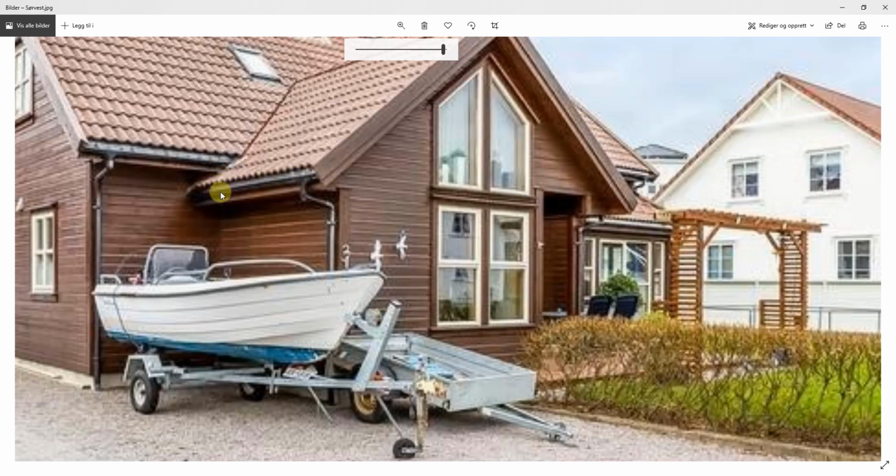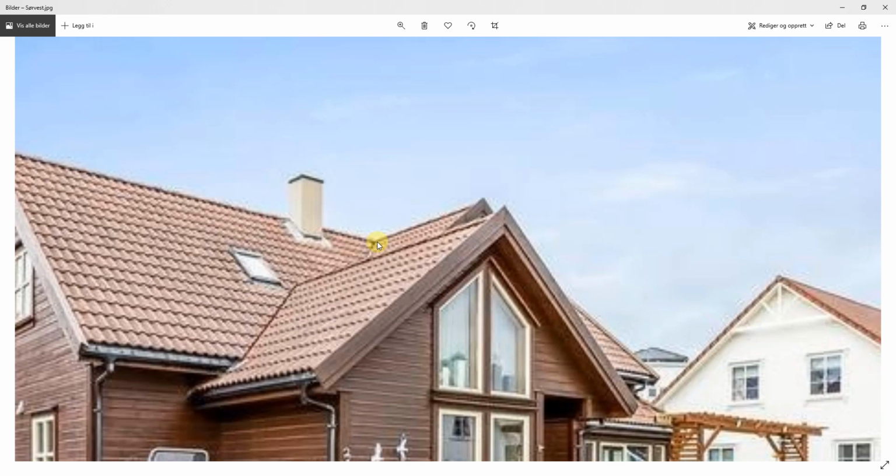I don't know, because on the inside you can see it is about 2.5 meters. But anyway, we see here this is not the same height, and that's very typical that this is a little bit lower than the main ridge. I think we should lower this maybe 10 centimeters or something like that, and see where we are then.